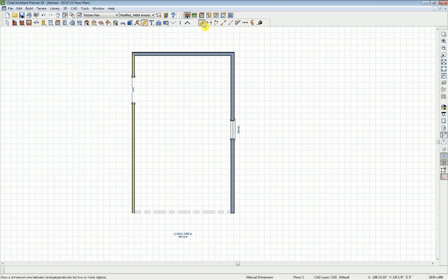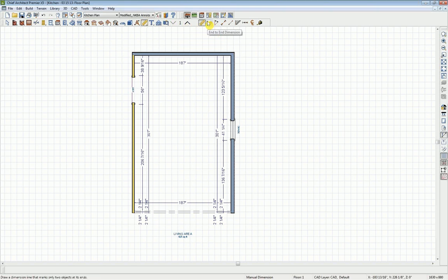In our dimensioning tools, we have a lot of different options. So you do have control over all of the different angles, interior dimensions, center line, and we do have a tape measure tool, another kind of temporary option, so that's pretty efficient for you. And then we have these automatic dimensions. So we can do the auto exterior. We can also do auto interior. So with one click, all of the dimensions will pop up for us, all of the openings, and locate to the interiors. So I'm going to use these dimensions.